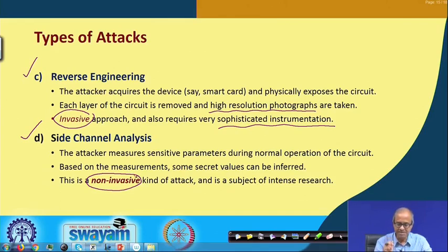We are measuring some sensitive parameters, we shall see later what these parameters are. These parameters can be temperature, it can be power consumption, current drawn from the power supply, electromagnetic radiation, and so on and so forth. Variations in these measurements, trust me, will give you a lot of information about what is going on inside the chip.